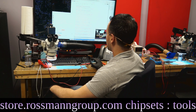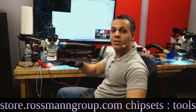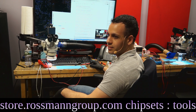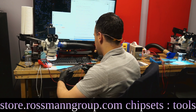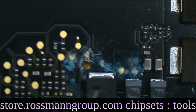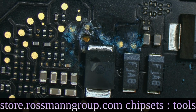Why do you think the resistor went bust? Well, that was water, so did you ultrasonic that already when we saw it? Yes. All right, so that was after ultrasonic, so most likely there was a liquid damage there that caused it. It looked like this stuff before I ultrasonicked it. I'll show you what it looked like before ultrasonicing on a board that has similar damage. So this is another touch bar piece of junk. And this one's going to be difficult because, as you can see, there's no chip around that area that's corroded. There's no marking. So there's no way to really tell what that area is for.